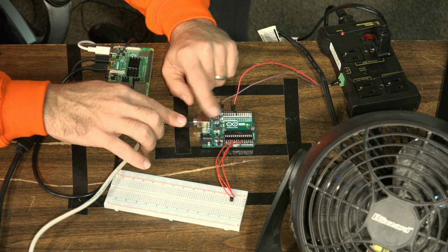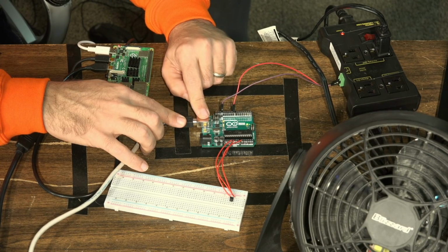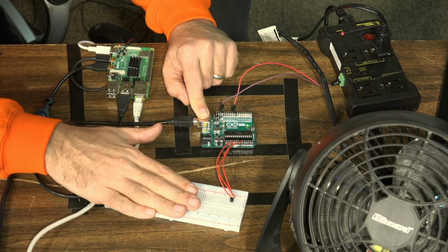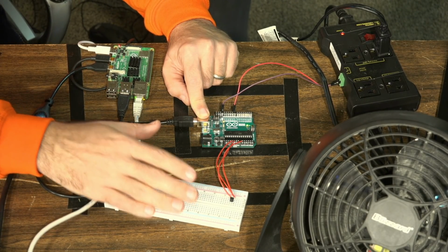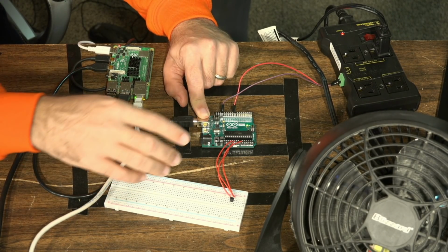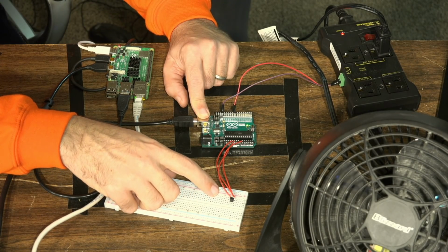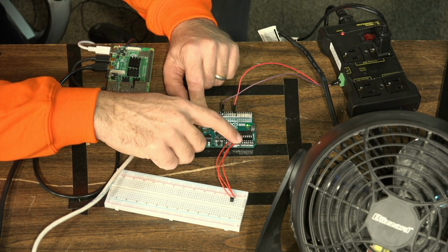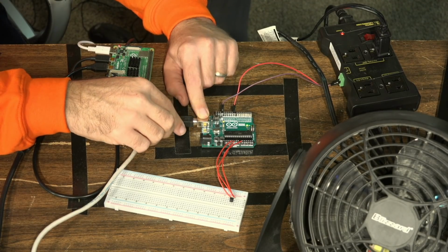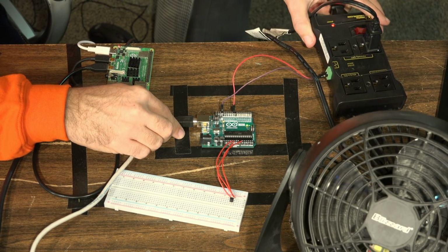Again, we're starting with our standard Arduino Uno, the same Arduino board that we normally use. On this side over here, we have our analog temperature sensor set up the exact same way we always do. The power is connected to the 5 volt, the ground is connected to the ground, and the sensor pin goes to A0 on the Arduino. Then we have this particular power relay.